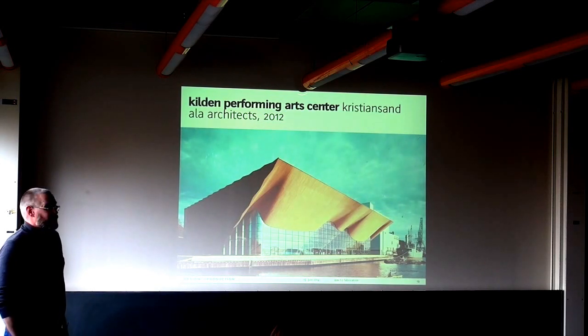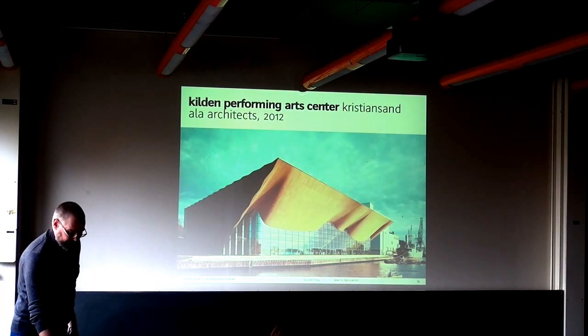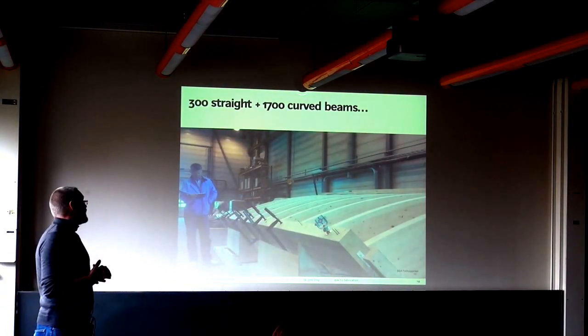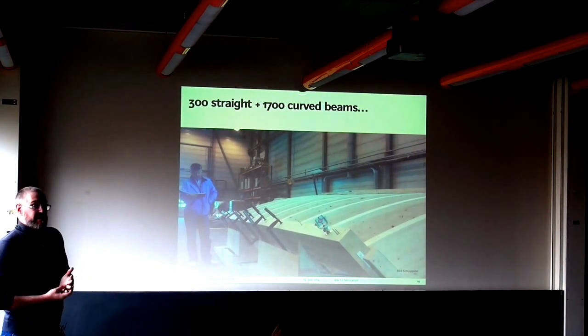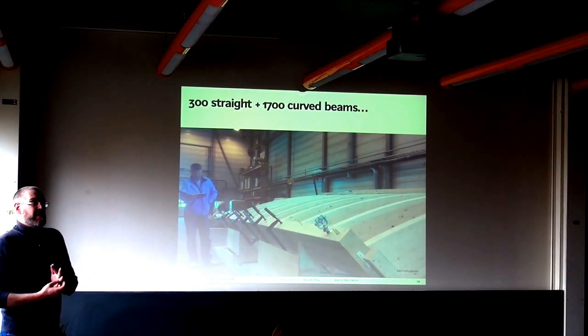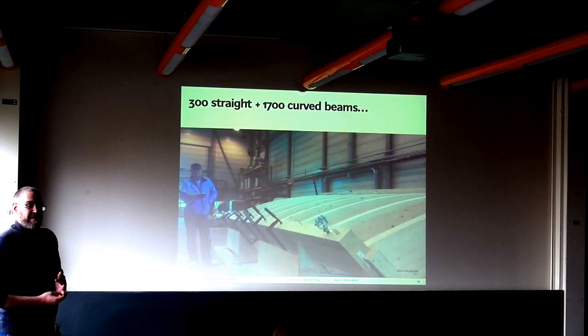And the tricky part here was to really get the precision that was required to get those straight 10 millimeter gaps running up the facade in a straight line. It was broken down into 126 facade elements that were prefabricated in a wooden boat builder's workshop about 100 kilometers from the building site. Luckily, we had the building site right at the water, so we could literally ship 50 square meter large elements directly to the construction site and hoist them up into the facade.